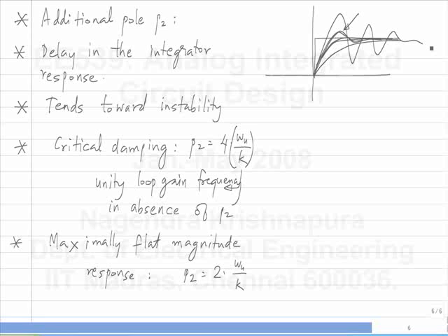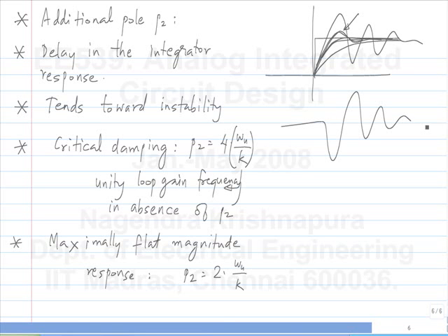That is if it's an ideal voltage source. Now, in a real voltage source, what will happen is there will be a small amount of disturbance and the disturbance dies down. If it rings a lot, that means that when you apply a step, the voltage will do something like this. This is not the behavior you want from a supply voltage, right? You would like the output voltage to be constant.